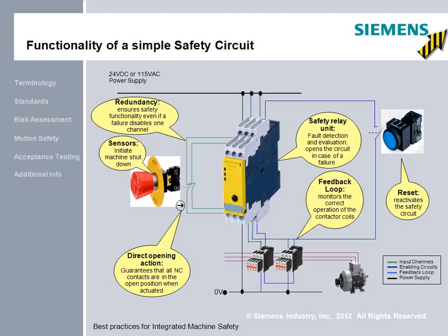Its job is to detect the open or close state of that emergency stop switch and to set its outputs accordingly. Its diagnostic purpose is to test and sense the wires going through the switch to look for opens, shorts, etc. The responders, or the actuators in this case, are two contactors near the bottom of the page.